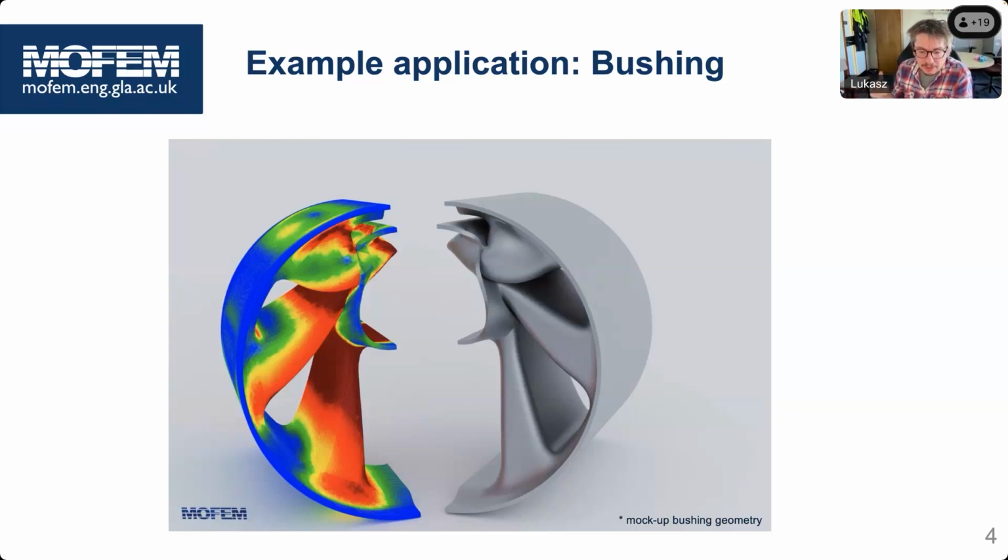So now we're moving to this, but in both cases we're using an energetic criterion. So in both cases we're using Griffith. We propagate the crack in the direction which is driven by maximal release of energy. But in the method which we propose now, we will not have an exact representation of the crack front.